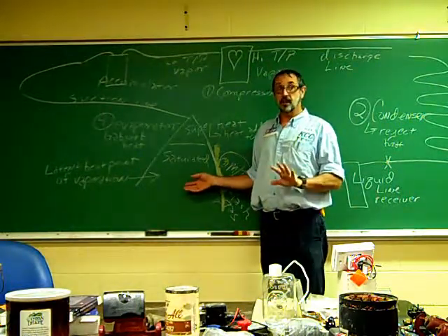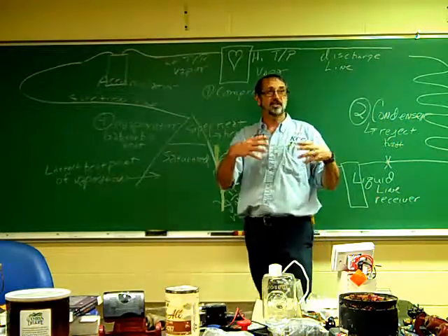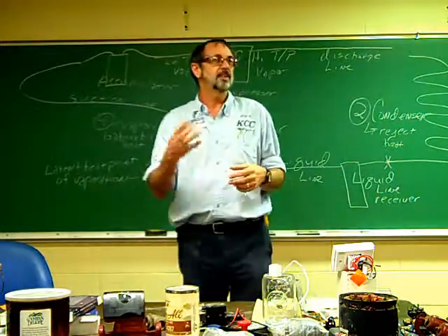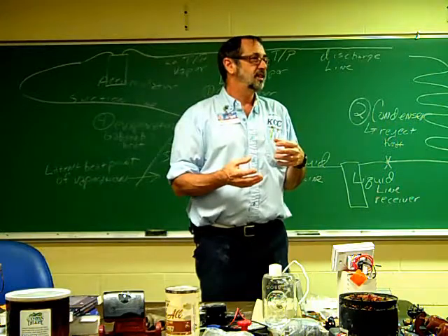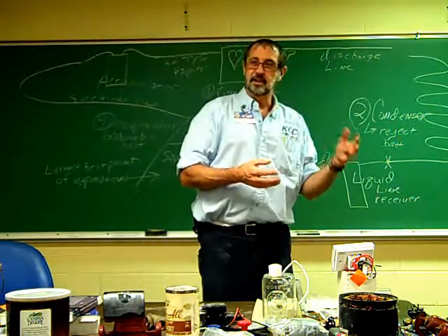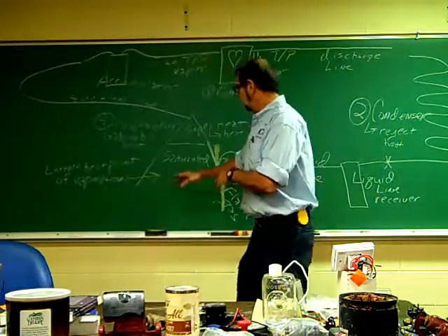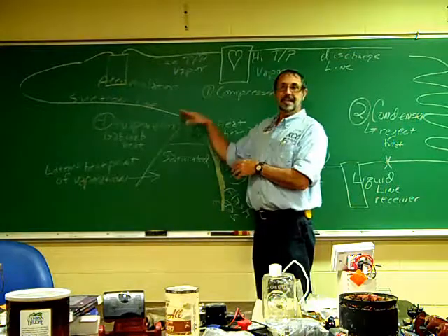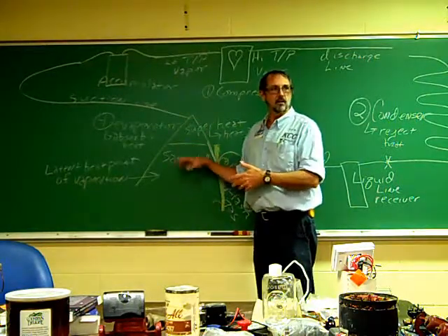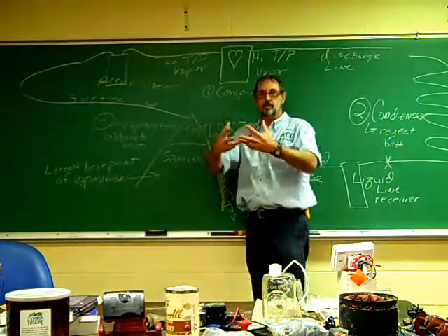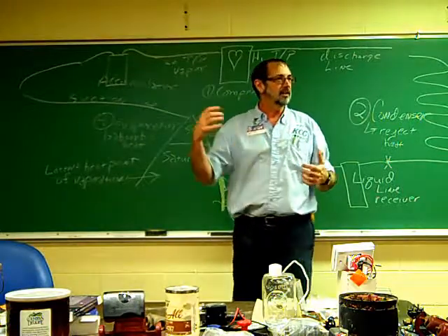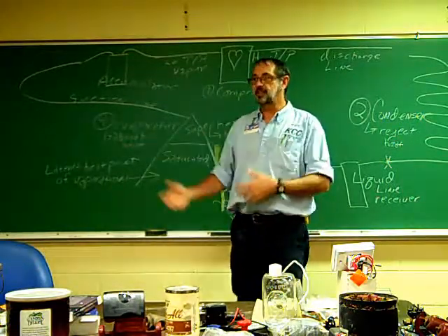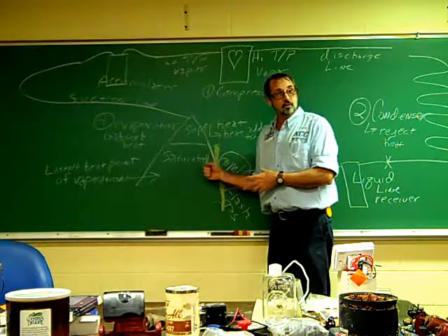Now, a couple of things we're going to talk about here. You will remember the definition that I gave you of refrigerant: any substance that as it changes state from a liquid to a vapor absorbs heat. Well, that's what's happening here. We're going to bring a heat-laden something, air, water, across the evaporator. We're going to absorb the heat out of the air or out of the water, and we're going to recirculate that. The refrigerant is going to absorb the heat.